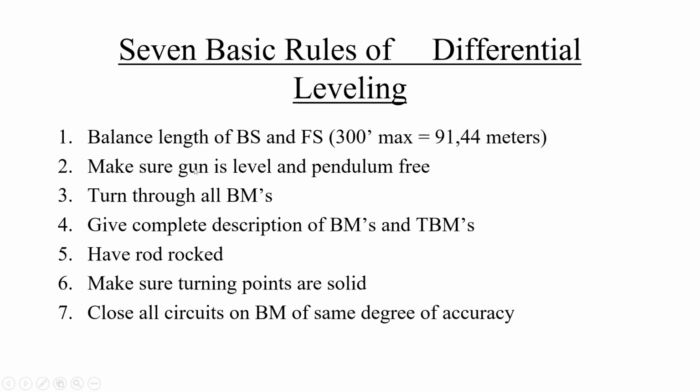We should make sure that the bubble of the telescope is level and the pendulum is free. Then we should turn through all BMs, give a complete description of BMs and TBMs, have the rod rocked, make sure turning points are solid, and close all circuits on BMs of the same degree of accuracy.